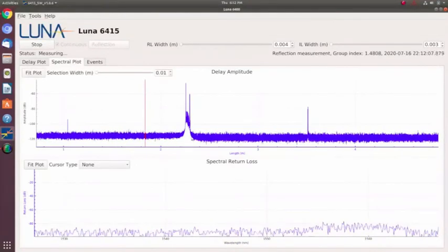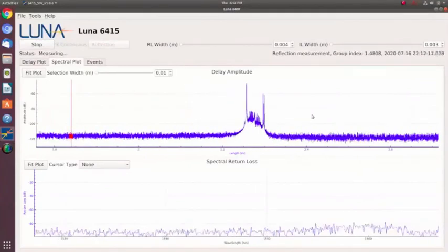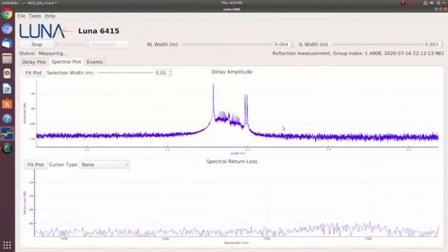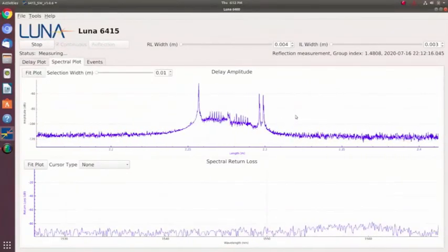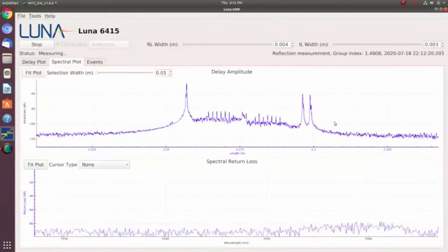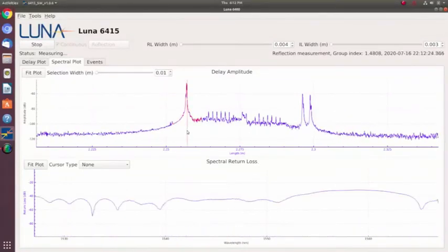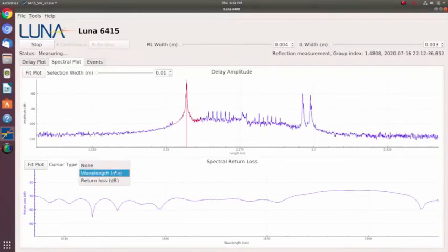Should say that those are grating coupled as well. So you have a fiber optic coming into a surface grating coupler into the device, and then 2 grating couplers out. We can look at the spectral content. So now I can choose just this peak, and I can look at its spectral content on the bottom. So you can see that's about a 30 nanometer scan. It's fairly broad, but it does have some spectral content, and that's really the spectral content of the grating coupler.